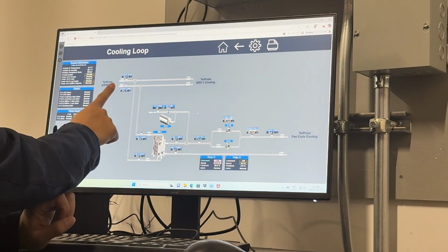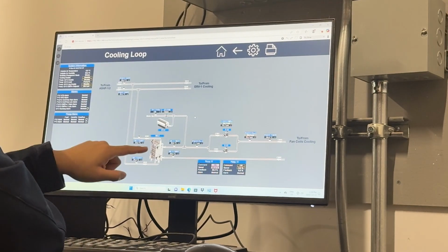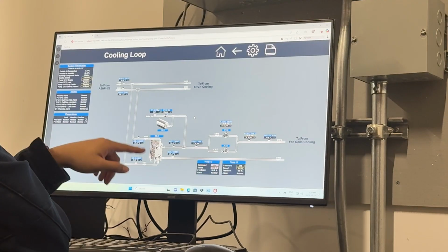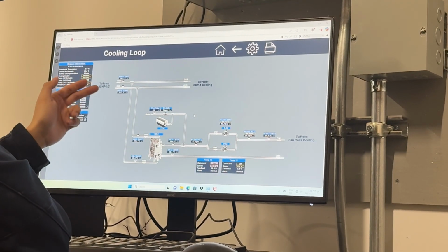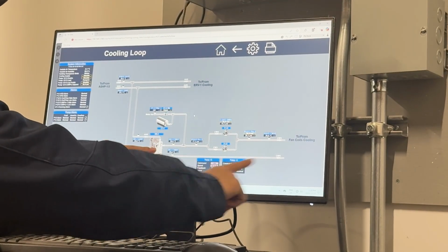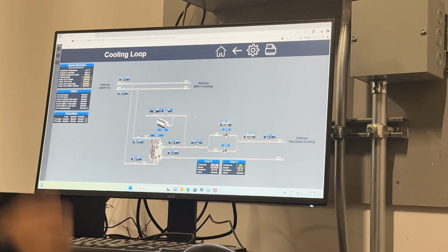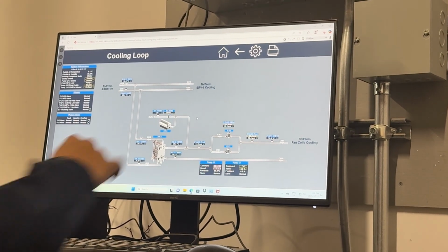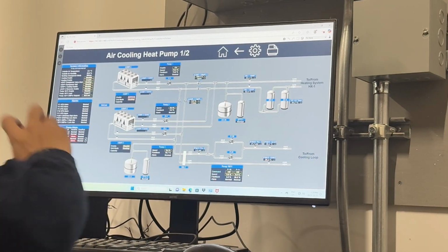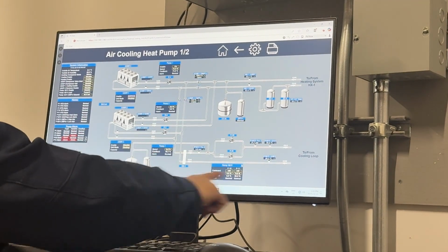So from air source heat pump 1 and 2, the cooling loop goes to the ERV or it goes to this heat exchanger, heat exchanger 2. Air source heat pump 1, 2 gives the heating to heat exchanger 2, then heat exchanger 2 will do the recirculation. So this loop goes to the fan coil unit, the suite fan coil unit downstairs. Oh, and here, differential pressure. I believe those two pumps are just at fixed speed. Fixed speed, yeah, because it's actually a closed loop, right?